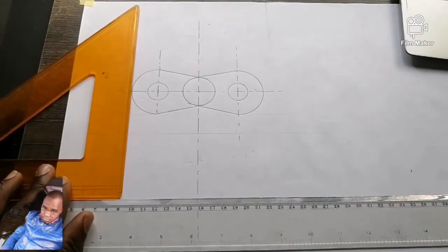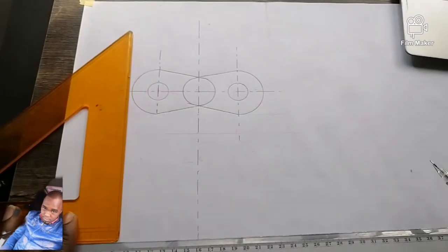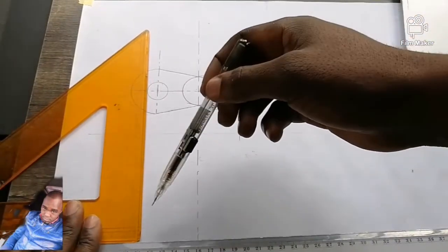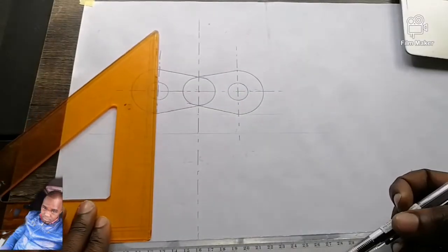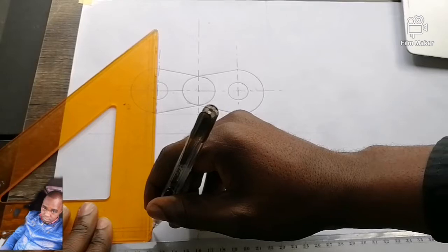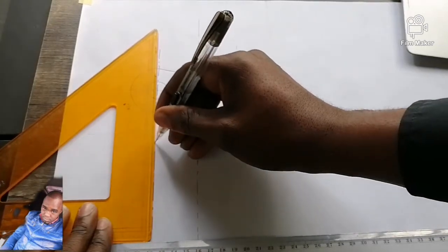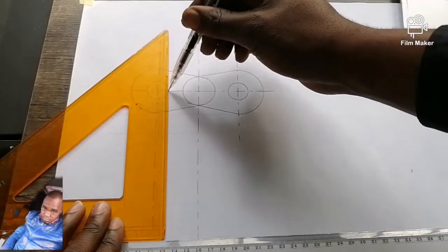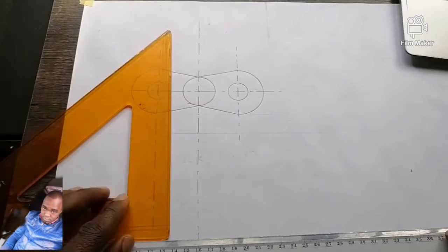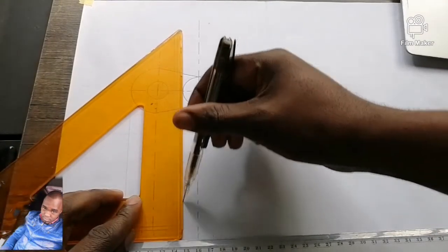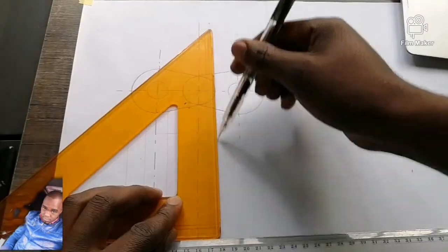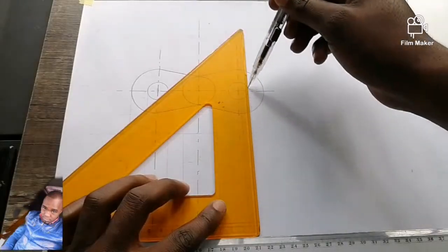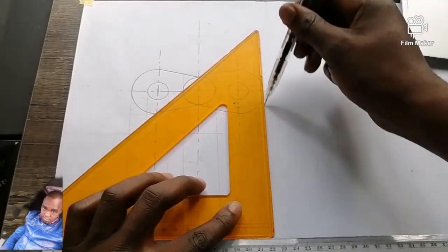So get this line faint. Let's go down a little bit. You draw it faint. You take this point faint as well. You can take this center. A center line is always dark. So all the points that are vertical, you have to construct them down faint. Take them like this. There you go.